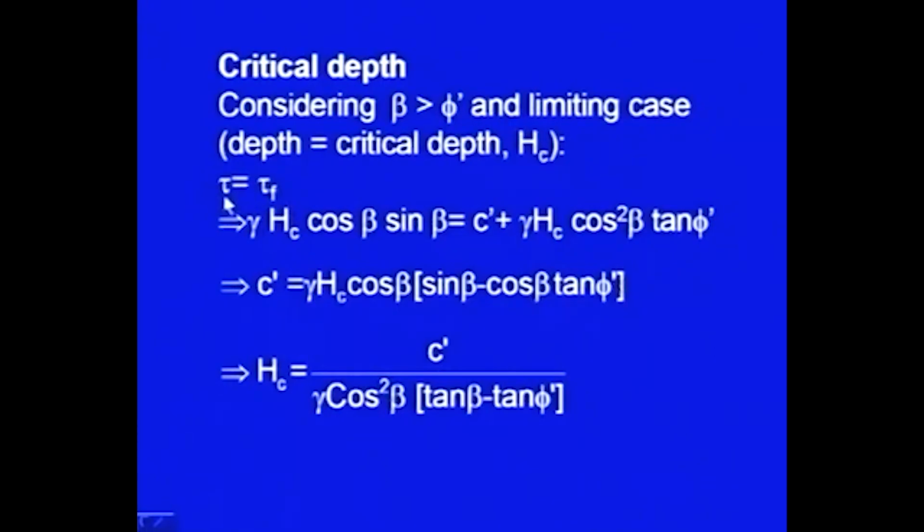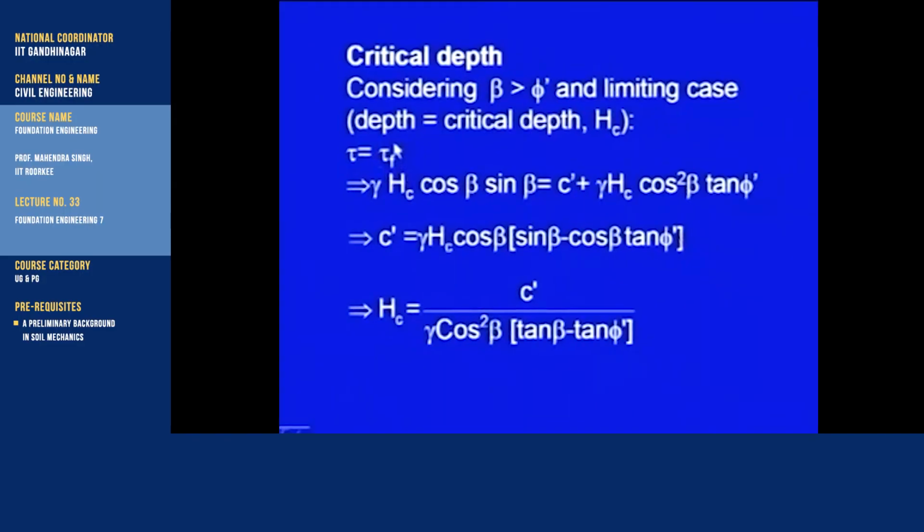What do we mean by this? The entire shearing strength which is available is being mobilized. So, you will be getting the maximum depth. So, this is the critical depth h c.